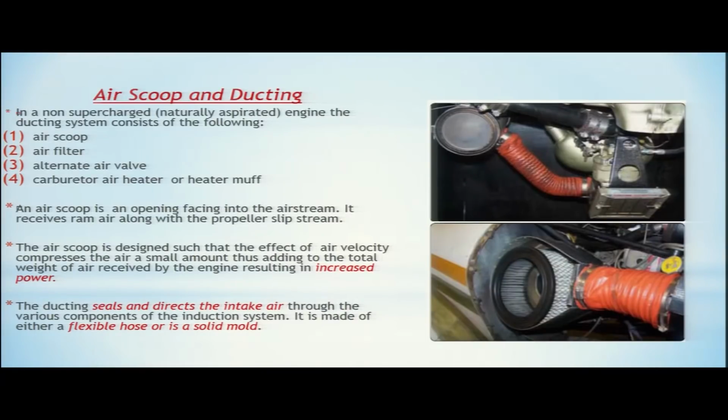The air scoop is designed such that the effect of air velocity compresses the air a small amount, thus adding to the total weight of air received by the engine, resulting in increased power. Now, this air scoop is designed in such a way that the air coming inside through this scoop is compressed, which results in increasing the total weight of air. So, once the air is compressed, the weight of the air is increased, and finally the engine power is increased.